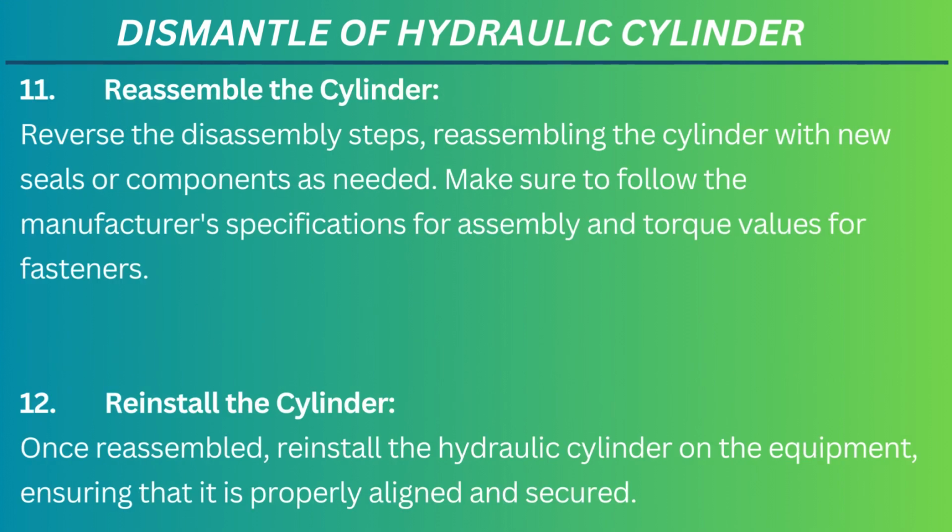11. Reassemble the cylinder. Reverse the disassembly steps, reassembling the cylinder with new seals or components as needed. Make sure to follow the manufacturer's specifications for assembly and torque values for fasteners.